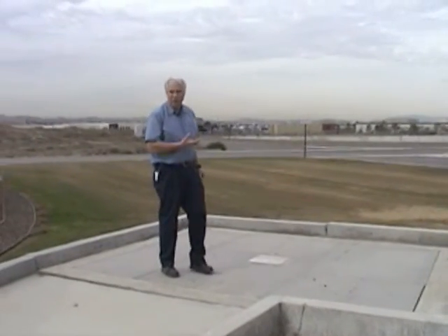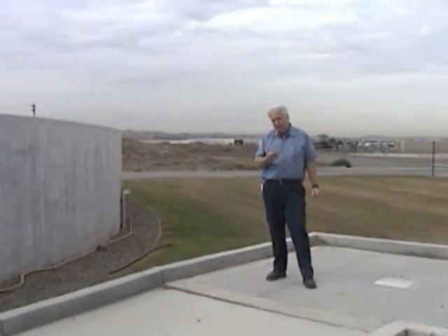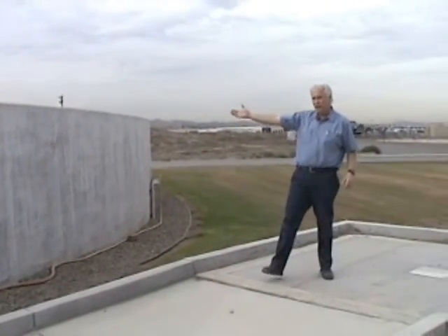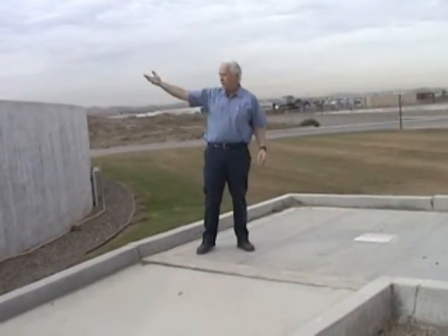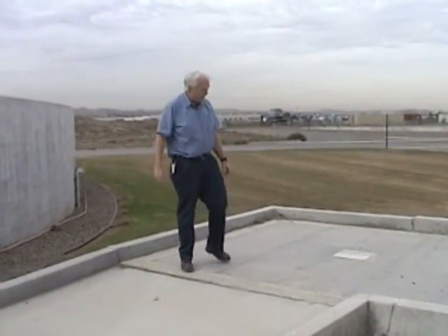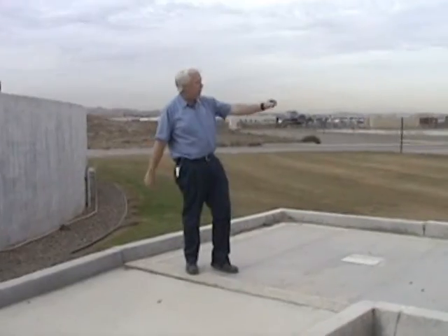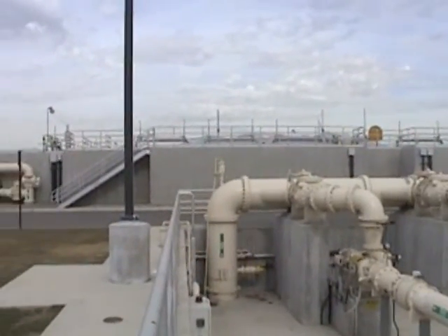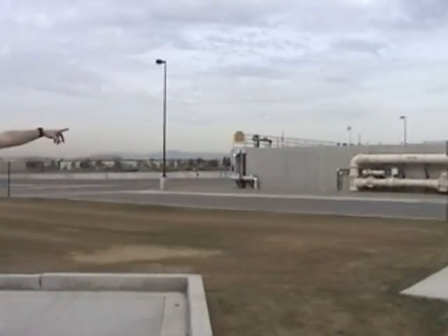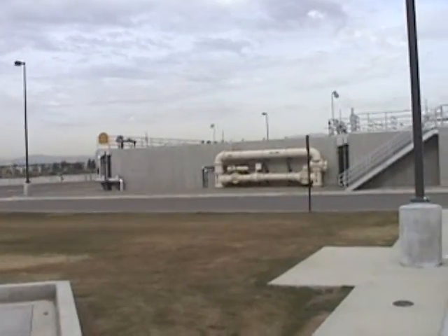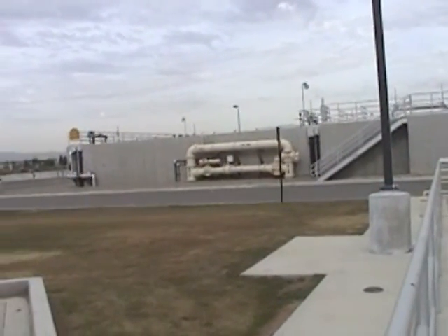If you're ever putting a secondary clarifier online, this valve has to be shut because you'll begin to fill the secondary clarifier, it will fill up, it'll begin to overflow this pit. So it's really important. And also, the secondary clarifiers are fed from that tank right over there, the aeration basins. You can see from where I'm standing how high that wall is, it's going to be a lot of liquid. So this is very, very important.